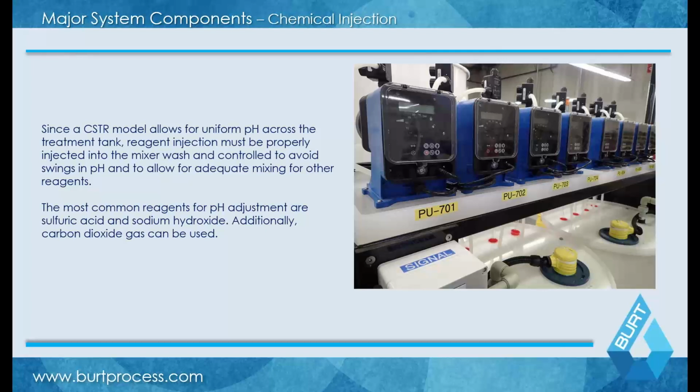So where you may have 50 gallons per minute flow, you may have 5 gallons per hour of your chemical injection. And that's because these chemicals are going to be, based on the pH scale, orders of magnitude stronger than even your strongest waste stream.